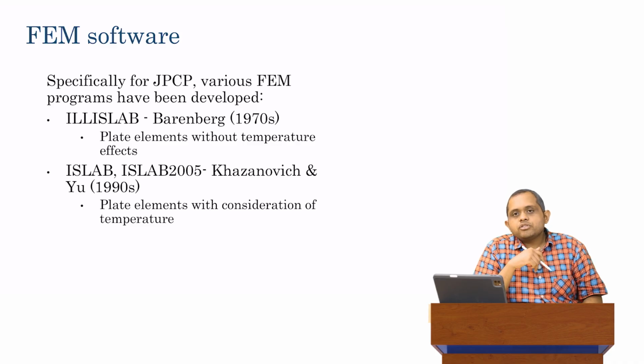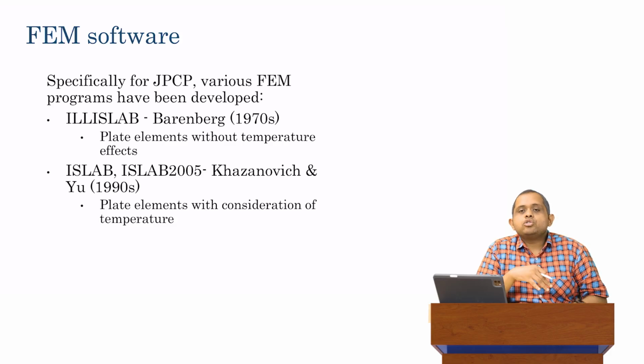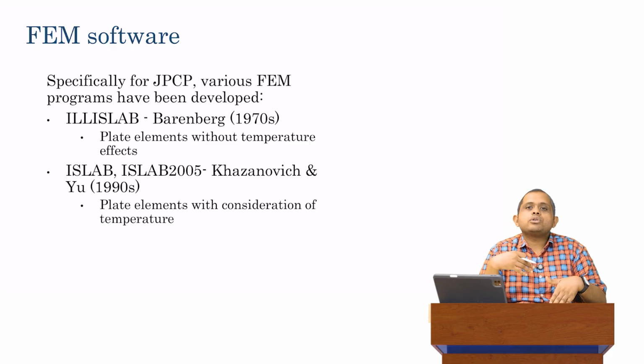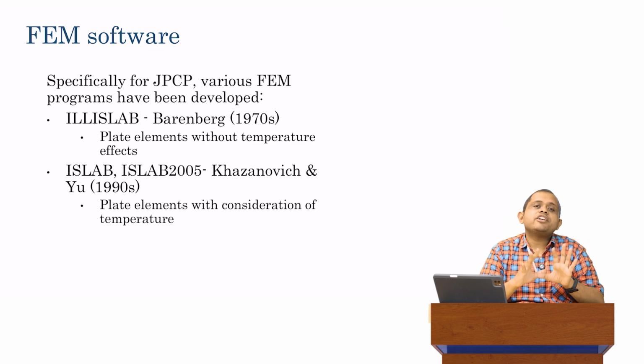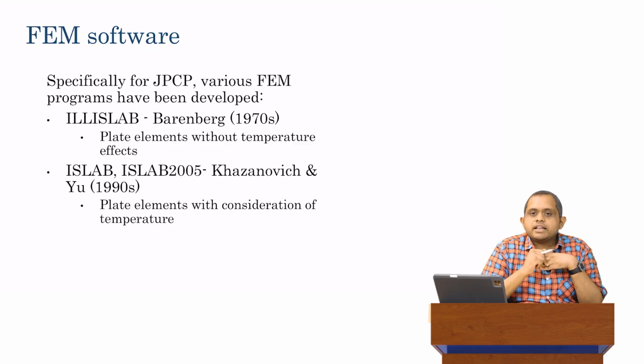Now, the previous programs which I discussed, whether it's the commercial or the open source ones, they are what we call general purpose FEM programs. That is, you can use it to analyze a JPCP pavement. You can use it to analyze a submarine under the ocean. You can use it to analyze a satellite in space. You can use it to analyze a building, dam, etc. General purpose. They can be used for any application, which is fine. And if that's what you desire, that's also fine.